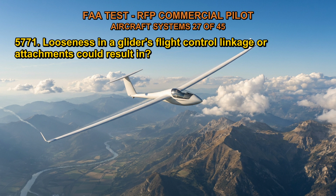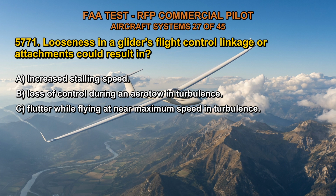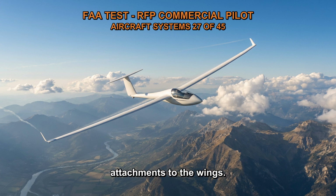5771. Looseness in a glider's flight control linkage or attachments could result in: A. Increased stalling speed. B. Loss of control during an aerotow in turbulence. C. Flutter while flying at near maximum speed in turbulence. The correct answer is C. Flutter can be brought on by loose parts in the control cables, linkages, hinges, or the attachments to the wings.